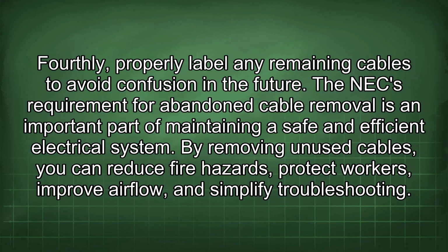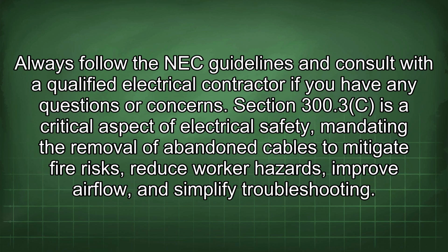The NEC requirement for abandoned cable removal is an important part of maintaining a safe and efficient electrical system. By removing unused cables, you can reduce fire hazards, protect workers, improve airflow, and simplify troubleshooting. Always follow the NEC guidelines and consult with a qualified electrical contractor if you have any questions or concerns.